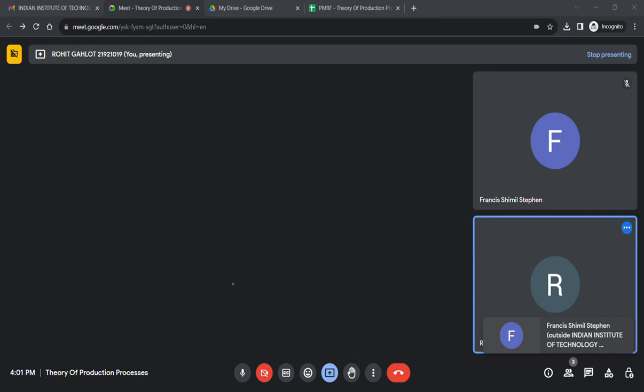In the top riser we take only this one area, but in the case of a side riser, both the end areas as well as the peripheral area come into consideration.